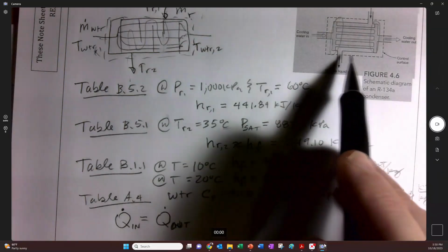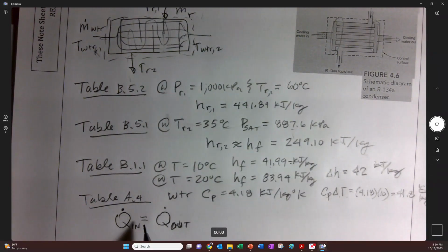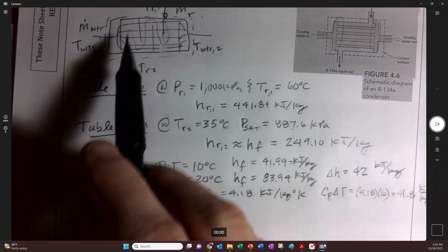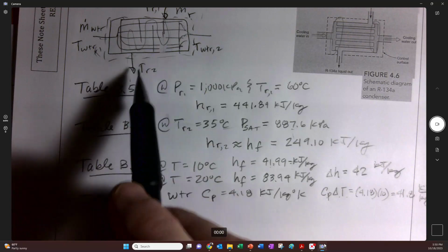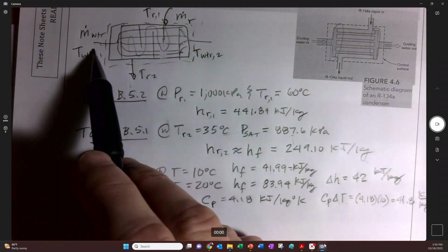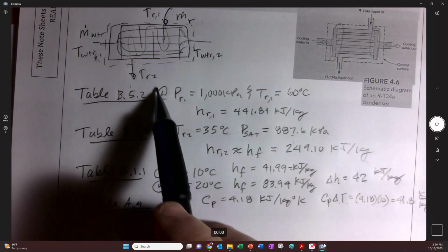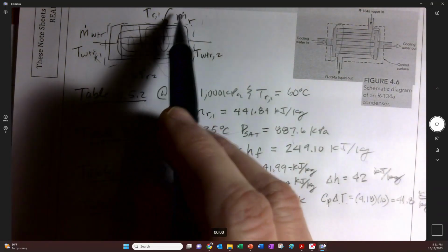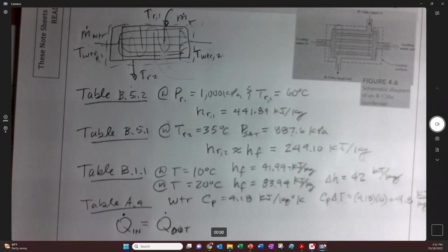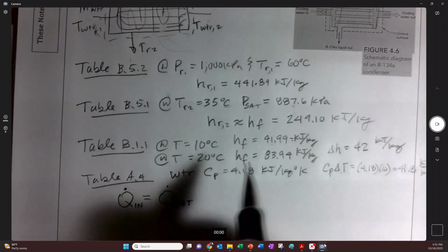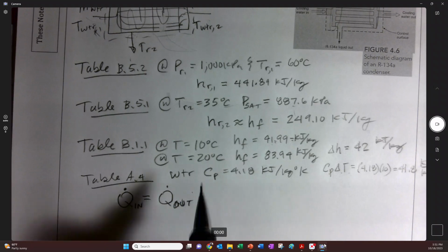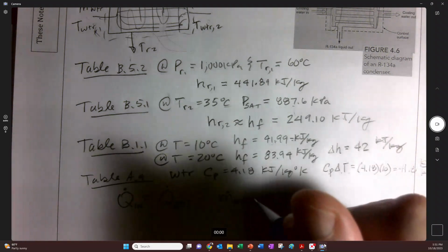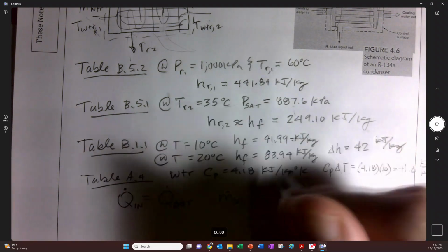We're not doing any of the heat transfer stuff we did previously, where we actually had the surface of the tubes, because it's all happening inside the control volume. So we don't really care about what the mechanism exactly is. We have the inlet and we have the outlet of both of these things, and as long as this thing is insulated and there's no heat escaping anywhere, the heat that changes from this fluid has to be picked up by that fluid. We don't have to worry about what's taking place inside. So this statement is good for us, and we will just say that m dot of the water times h of the water.